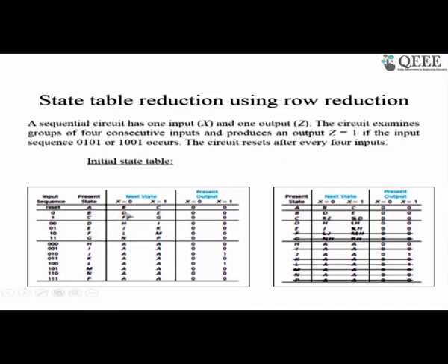Now we have these cases. After getting 2 bits, we can be either in D or E or F or G. So far 2 bits have been obtained, accordingly we have gone to D, E, F, G. The third bit can be a 0 or 1. If a 0 or 1 occurs in D, let us say we go to H or I. Similarly in E we go to J or K, in F we go to L or M, and in G we go to N or P.